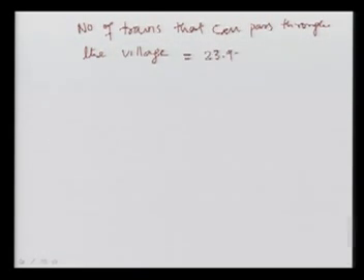It came out to be 23.92. Okay, but then obviously the train has to be a full number, not a fraction. So the actual answer should be 23 trains that should be allowed to pass through the village. It was an interesting problem. It involved some practical aspects of what we have learnt, and also applied some concepts of simple conversion and some sense of emission relative to the air quality standards or air quality norms that we need to attain. So we'll move to the next problem now.